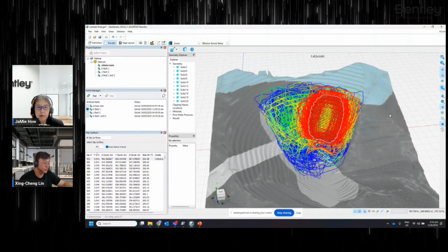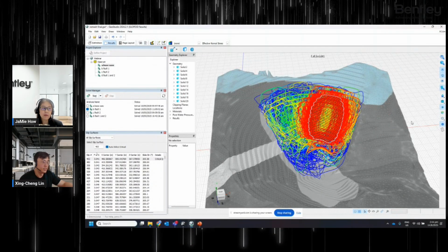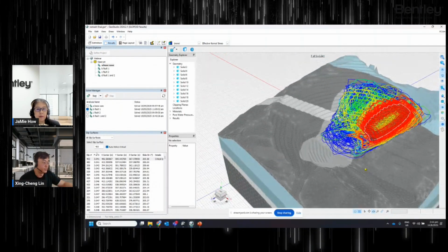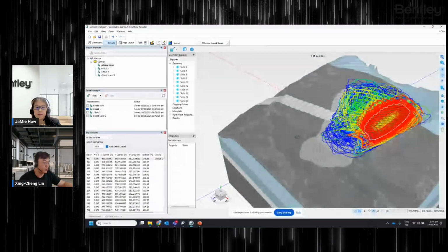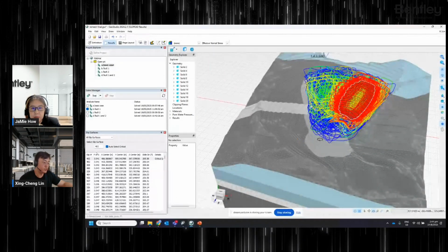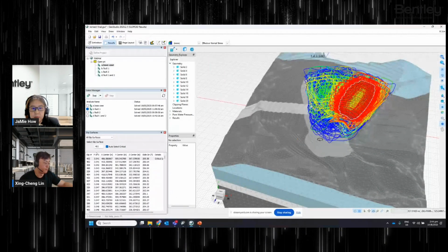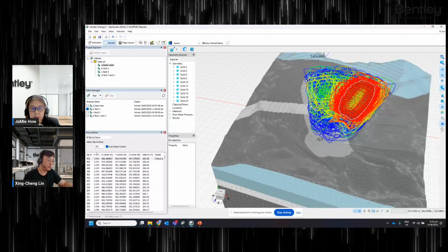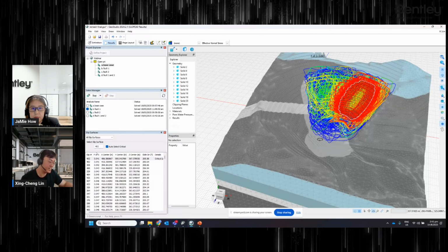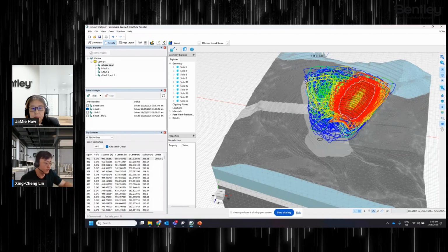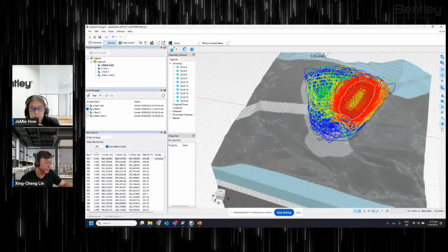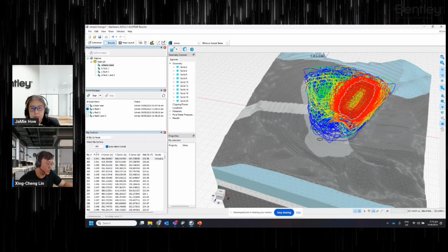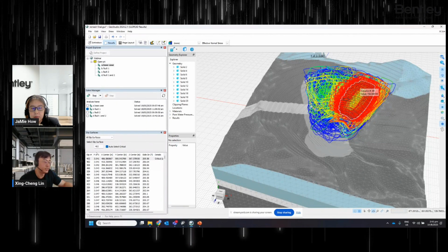choose to display all the 900 trial surfaces. And this is how it looks. It gives us a good idea how the cuckoo algorithm searches for the most critical slip surfaces, as given by our constraints. Remember how we imposed constraints on the search by defining the extent of search. That's why all the slip surfaces fall within the range that we defined earlier, and our critical ones sit within this domain.